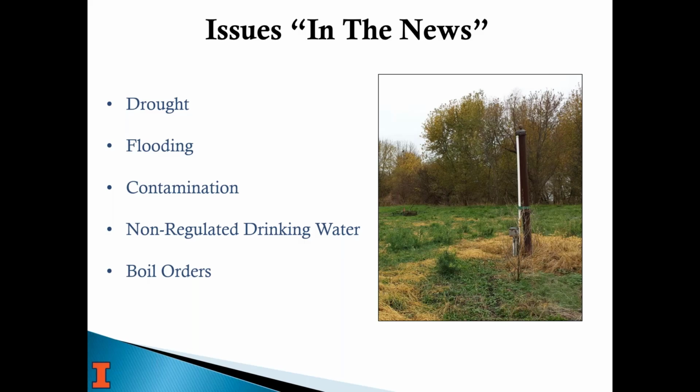It's welded steel. And unless the annulus, which is the area around the casing, the borehole has to be a little larger than the well you're going to put in, and then you backfill around the casing with clay or cement to seal it. If for some reason that annulus wasn't sealed properly, then water could go around the outside of the pipe and get down into an aquifer. But typically that's not going to happen. But it just brings to mind there are ways to deal with all these situations.